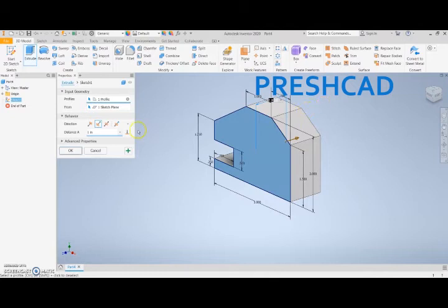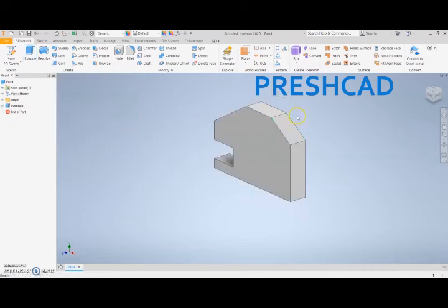So this is the extrude command up here. That's what is used for adding the thickness here. So let's change the dimension of the thickness. Here is 1 inch. So we will change that to 0.5 inch. Sorry, 0.5, and that's it. See, it's changed. So okay, and here we have our 3D object.